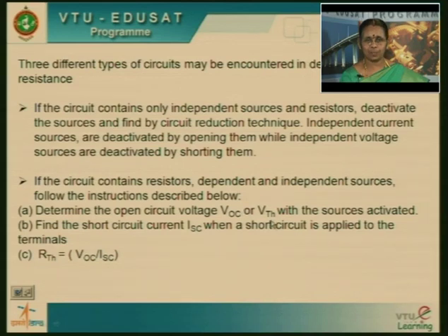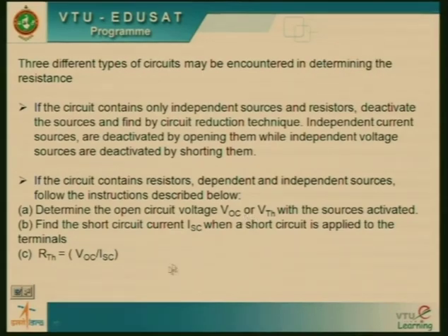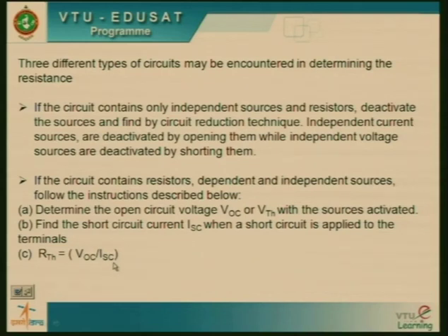You have open circuit voltage VOC or V Thevenin, and you have the short circuit current. So knowing the voltage and current, by applying Ohm's law, you can find out the resistance or the impedance, which we call here R Thevenin, equal to VOC by ISC.